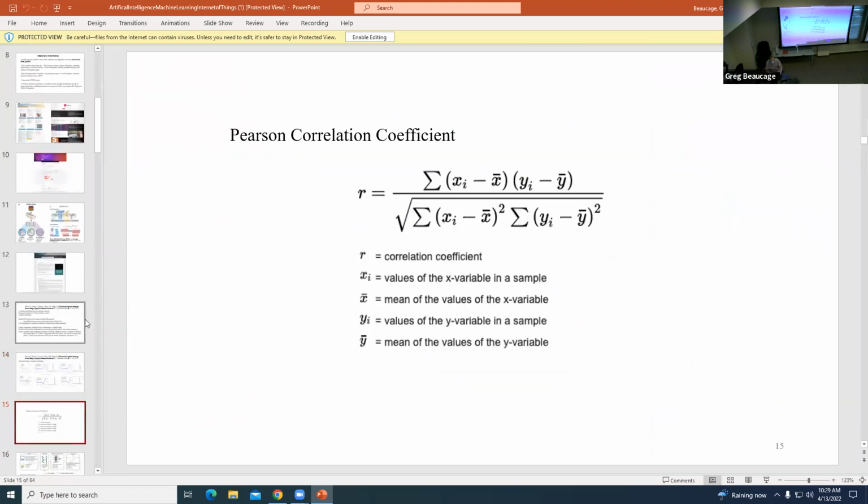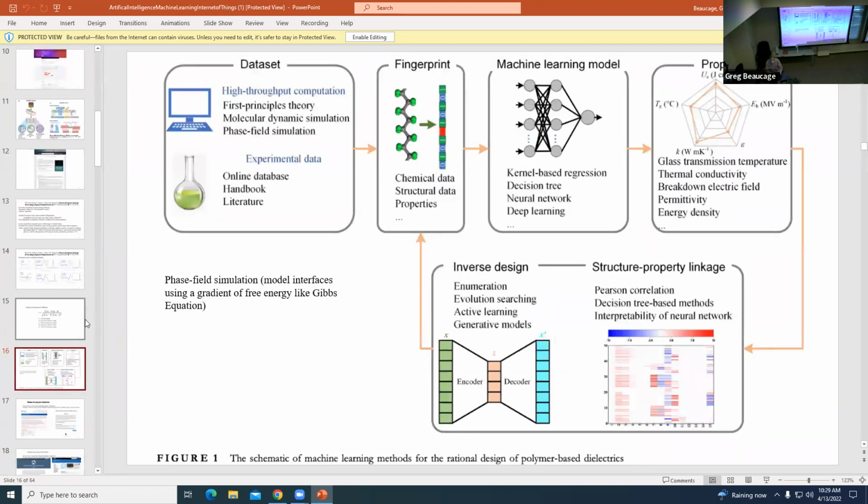There are these other areas though. So anyway, he's going to say, I want to make a super dielectric material. So it's going to have a dielectric constant and it can't have a dielectric breakdown, which means if you put a high enough voltage on anything, it'll arc across it, right? Then it'll heat up in that case. You need to know thermal behavior too. So it has to have good thermal behavior, and it has to have a high dielectric constant, and it has to have no breakdown. And then also the dielectric constant is frequency dependent.